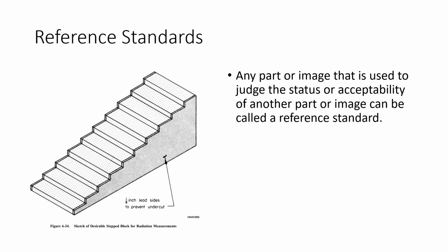So a lot of times we have reference standards for ultrasonic testing. We'll drill holes in a piece of metal or put a crack in there, and then we'll find that crack. We know where that crack is, and then once we get into production, if we find something similar, okay, we know that that crack looks like what a crack looks like because we found it on our reference standard, and we're finding the same thing here. So that's what we do with reference standards.